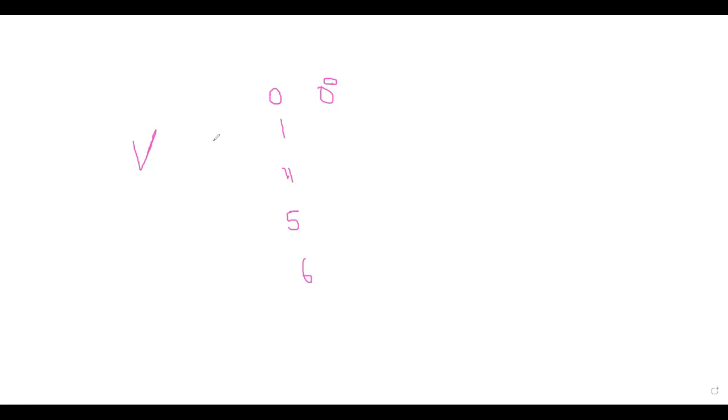And if it is 11 o'clock, suppose it's 11 o'clock, then this phasor is leading: the LV is leading the HV by 30 degrees. I mean, 330 degrees lagging represents 30 degrees leading in a simple way.